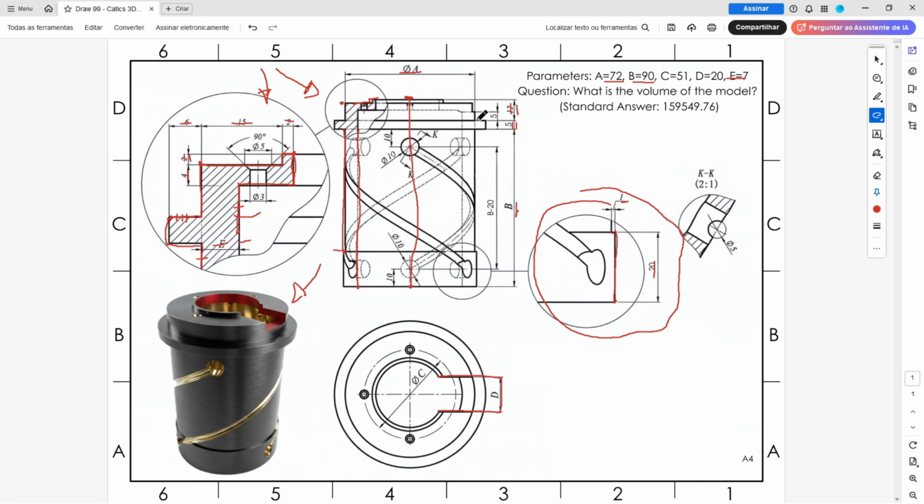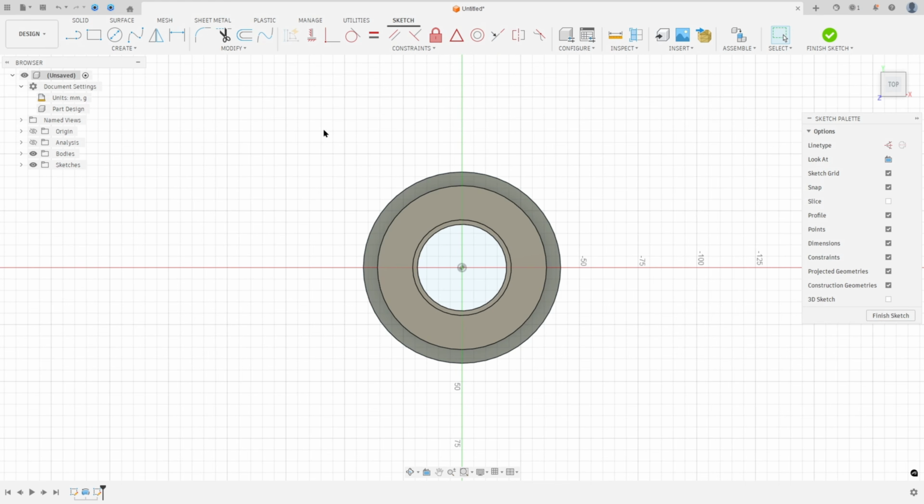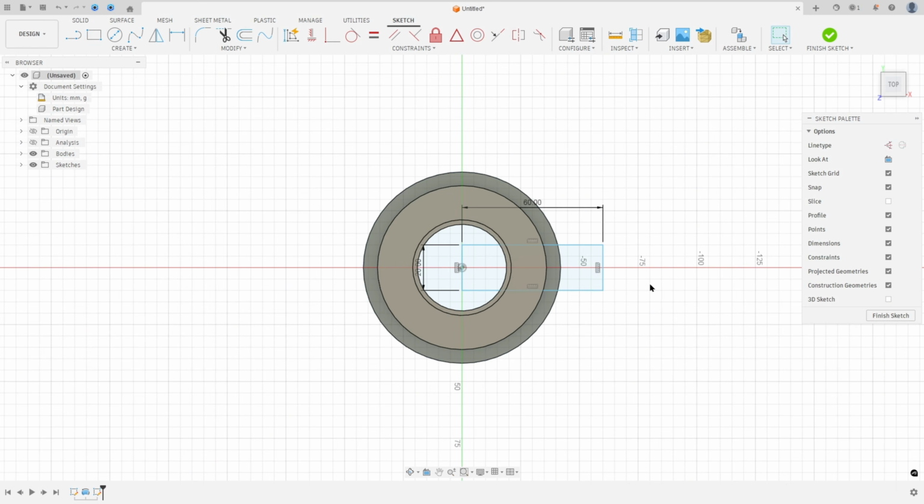To create this cut, we will select this face here to make a sketch. And here we'll make a rectangle. And the distance between these two lines here is letter D, 20 millimeters. So go to create a sketch and select this face. Now select the 2-point rectangle, make a rectangle here. The distance here, 20 millimeters. And here can use 60 millimeters and press OK. And go to constraint, select the midpoint, select this line and the center point here.